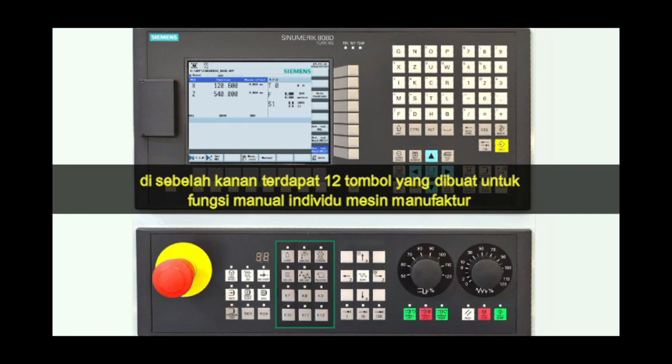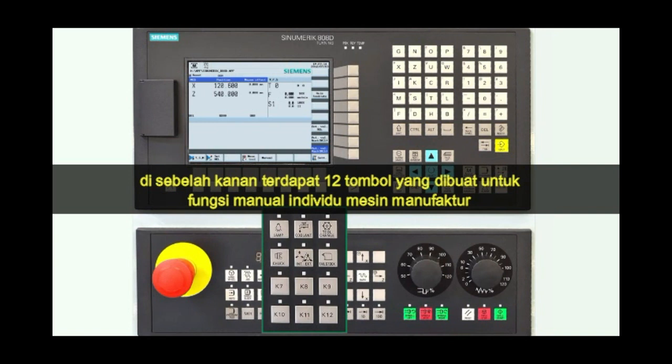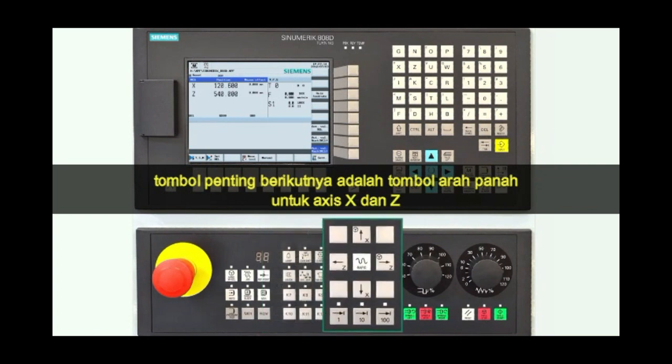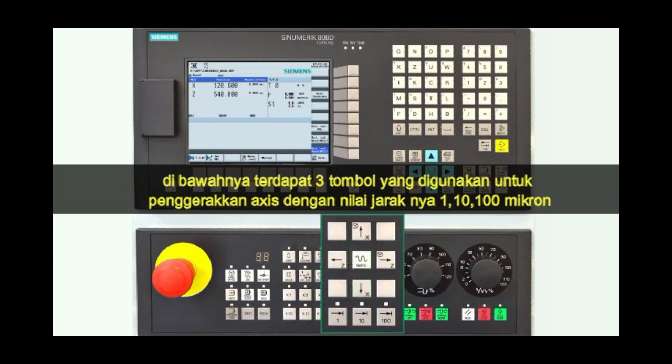On the right, you can see 12 buttons which are made for individual functions by the machine tool manufacturer. For example, activating and deactivating of the coolant. The next important keys are the direction arrows of the X and Z. When you hold the middle rapid button and the direction of the axis, it will move in rapid mode. Below there are 3 keys. You use them for moving the axis in a defined length, which is 1 micron, 10 microns or 100 microns.